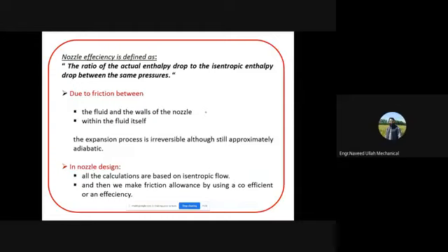So nozzle at the design condition and nozzle off the design condition. We discussed these things, okay. And I also told you that ideally we should have the nozzle at the design condition, but sometimes we deliberately have the nozzle off the design condition, and I gave you the example of the under-expanded nozzle in the case of the rocket initial firing, okay, right.